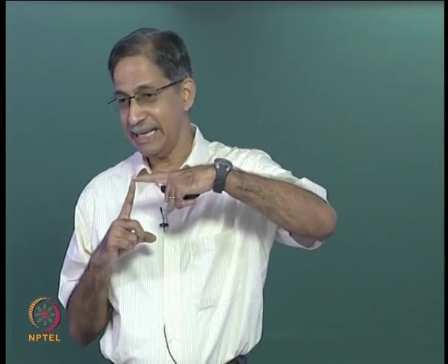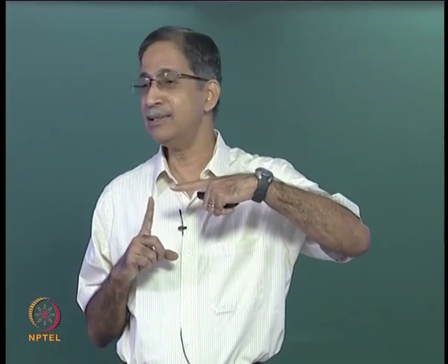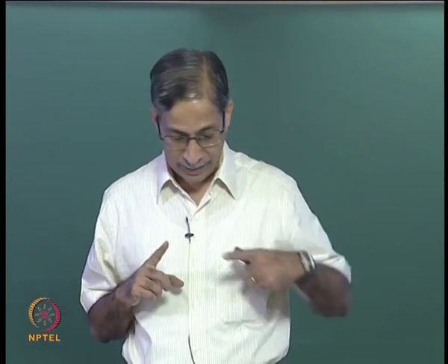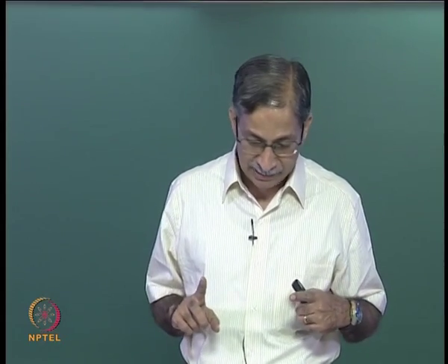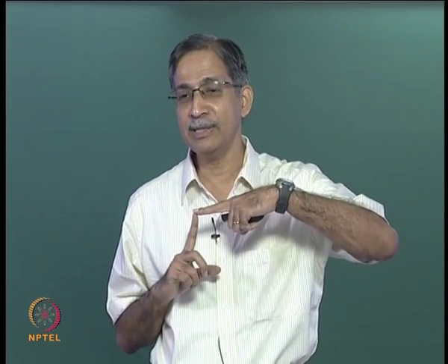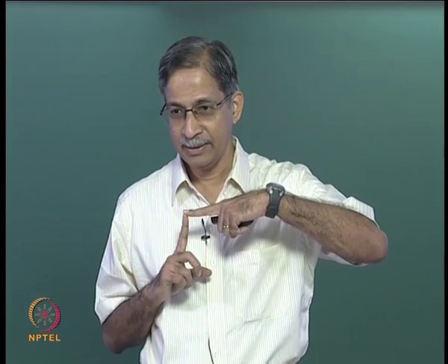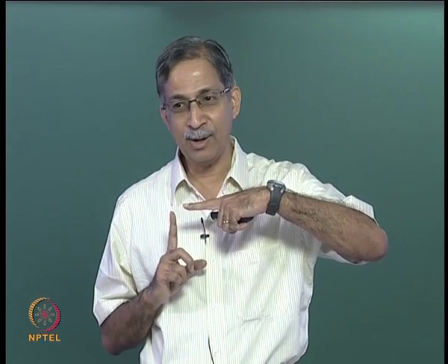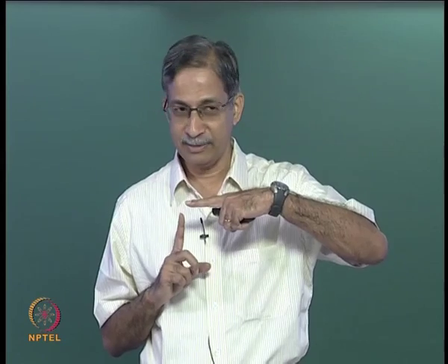I will tell you one way to understand. Remember when we talked of internal hinge, usually you have a parent-child relationship. Now clearly element 3 is a child, it badly needs elements 1 and 2 to hang on to for its own dear life, right. So the child cannot take loads when the parent is loaded.